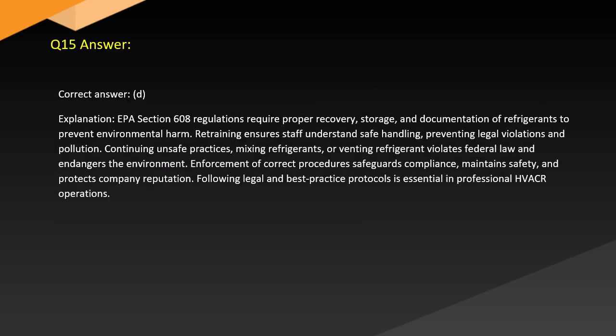Answer. Correct answer: D. Explanation. EPA Section 608 regulations require proper recovery, storage, and documentation of refrigerants to prevent environmental harm. Retraining ensures staff understands safe handling, preventing legal violations and pollution. Continuing unsafe practices, mixing refrigerants, or venting refrigerant violates federal law and endangers the environment. Enforcement of correct procedures is essential. Compliance maintains safety and protects company reputation. Following legal and best practice protocols is essential in professional HVACR operations.